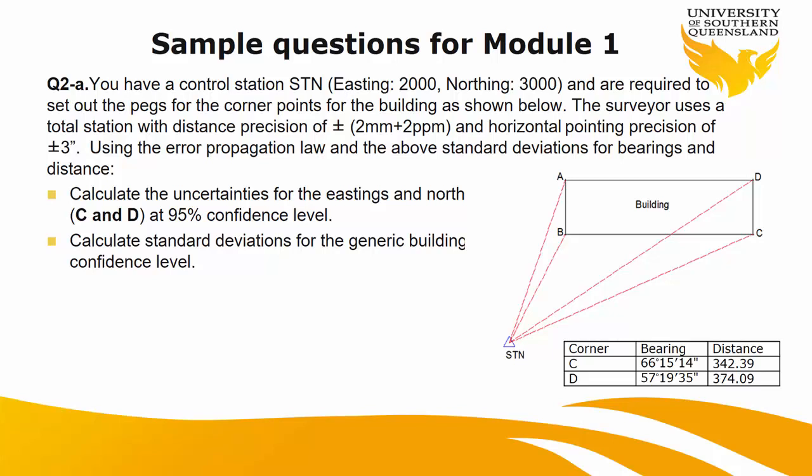What else? That's it, pretty much, yeah. So you know the magic number to convert, or if you don't, what's that? 206265. Yeah, you have to divide by that. If you remember that, if not, put it in your calculator somewhere. So put it as a formula so you know how to convert. These are the common mistakes I found during the time I was marking the exam. Many students forgot to convert, they forgot to find a sigma distance, or they do it for one distance, they don't do it for both of them.